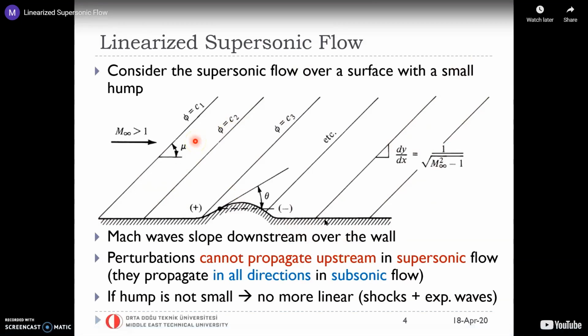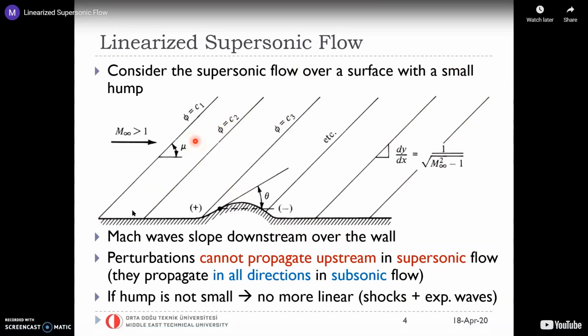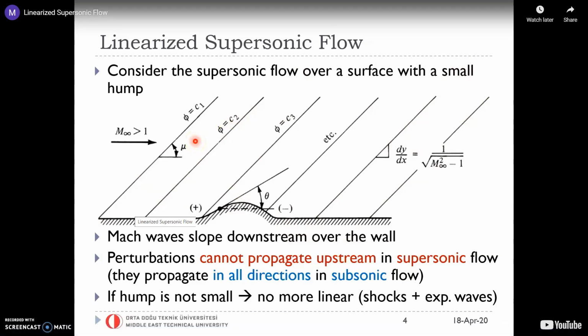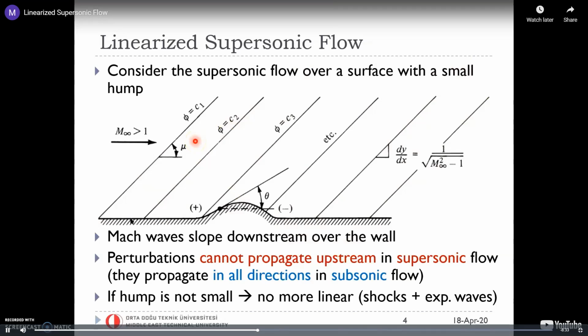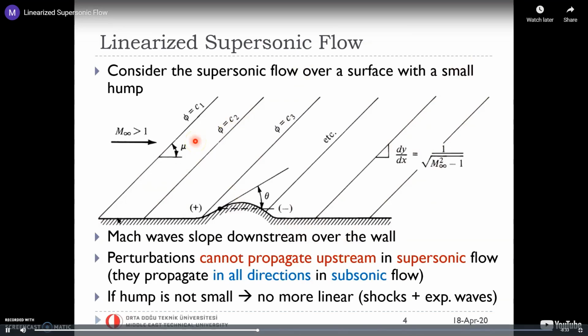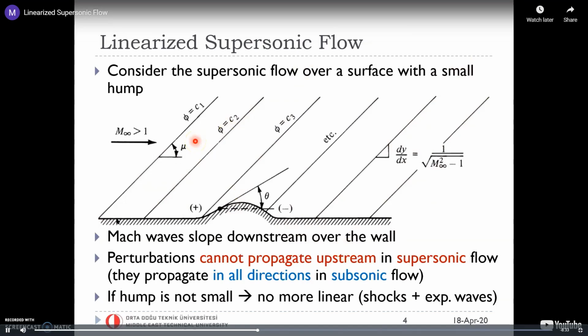It is so smooth that when the flow passes, on any point on this surface, it does not create absolutely any disturbance to the flow, okay? No disturbance. Of course, that's not realistic, right? No one can manufacture such a surface in the world. So our surfaces always have some kind of roughness. Maybe they are very low roughness values, but they always have some roughness, which means that our surfaces will always generate little disturbances to the flow.